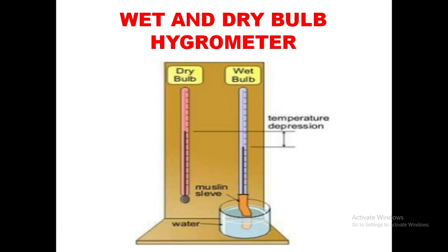Psychrometer or wet and dry bulb thermometer consists of two thermometers. One is kept moist with distilled water and a sock or wick. At temperatures above freezing point of water, evaporation of water from the wick lowers the temperature. So the wet bulb usually shows a lower temperature than that of the DBT, that is dry bulb thermometer. When the air temperature is below freezing, the wet bulb is covered with a thin coating of ice and may be warmer than the dry bulb.